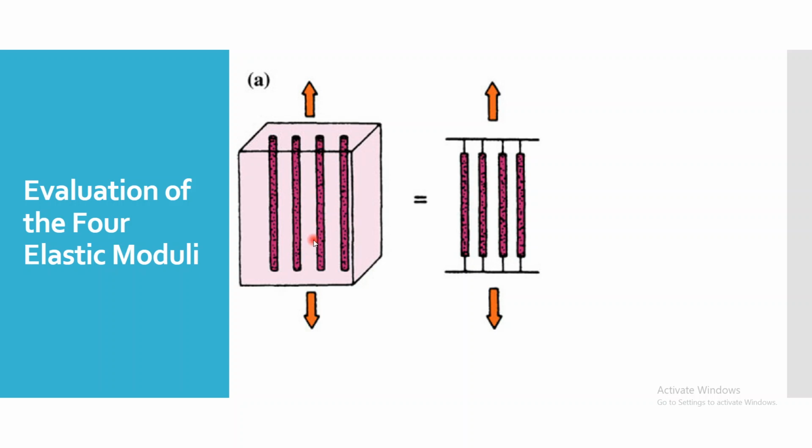Okay, so that is along the length of the fiber, and obviously the Young's modulus is also higher in this direction, that is longitudinal direction. In the same way, if I load the fiber in the transverse direction, then the deflections or the breakage of the fibers is very less when we look into its transverse properties. So that's why we should calculate these elastic moduli in two directions. One is longitudinal direction, another one is transverse direction.